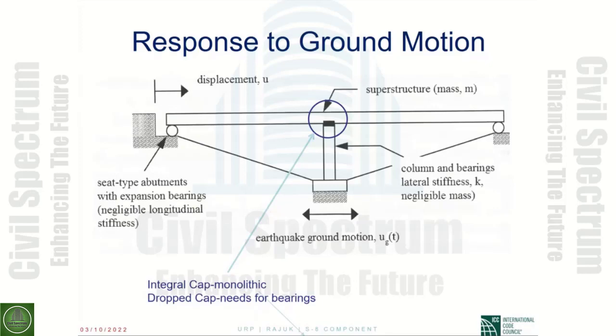That's why for the back wall, we actually detail it so that it will fail during the longitudinal motion, so that we don't damage the piles of the abutment. After the earthquake, we can come back and use the same abutment, fix the back wall, and take care of that detail.